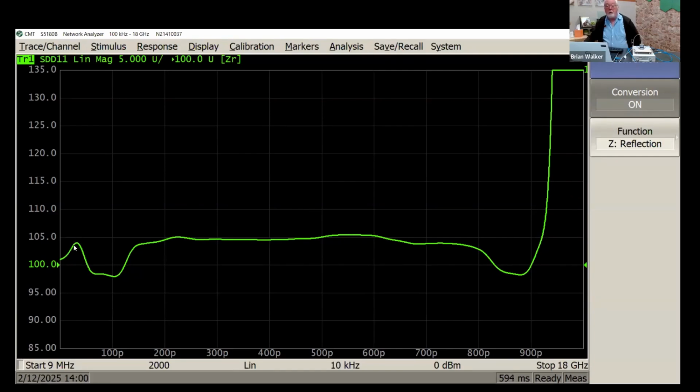the connector has a little bit of a bump. What's this little business here at the beginning? That's where the traces are fanned out in a V shape before they come together. And then they come together, and the impedance becomes about 105 ohms. And then the same kind of things are happening on the far end. And of course, it's open, so the characteristic impedance becomes undefined. So I'm using a 2-port VNA to make a differential measurement, and it was very simple to set up. And that is the end of my demonstration.